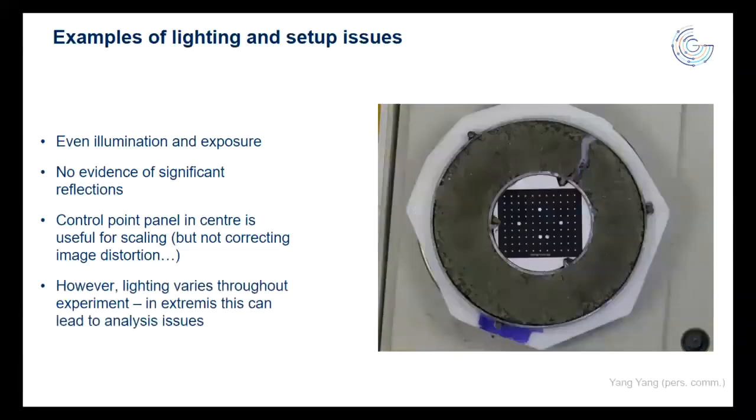The downside is this is in a lab environment relying somewhat on ambient light. So throughout the day, the ambient light is changing, okay? Now, the algorithm that we use in GeoPIV-RG can account for this to some degree. It's semi-invariant to the ambient overall light intensity in the image, but it's not perfect. And this was really quite challenging, even in spite of using that zero normalized cross-correlation algorithm. So shroud the sample, use artificial light, control it at all times would be my takeaway from that one.